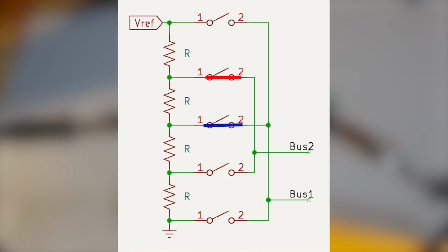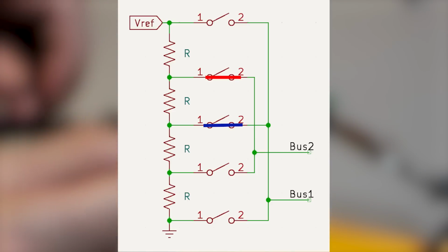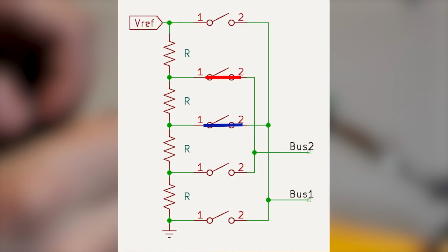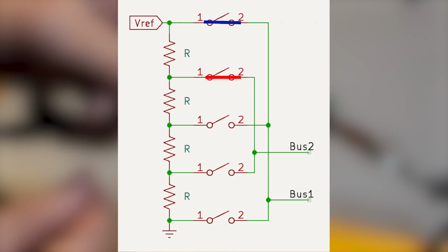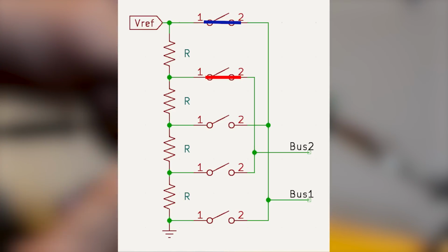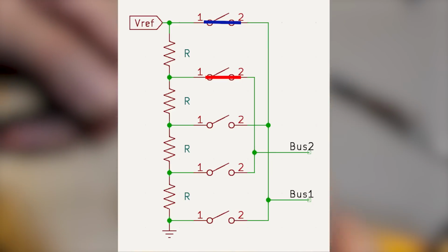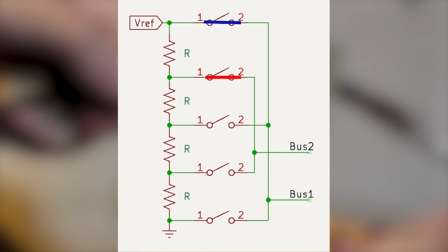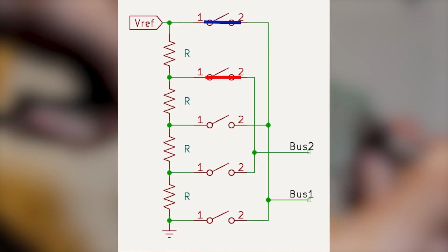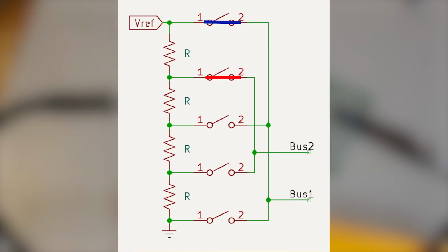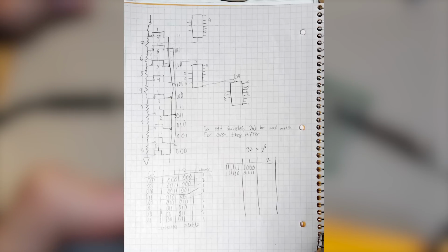In fact, when using this system, each bus will alternate between being V-low and V-high. And increasing the input code will only toggle one switch at a time, which means each bus will take turns incrementing their count. This reduces switching disturbances on the output, and even better, it greatly reduces circuit component count. You will, however, have to spend some time figuring out how exactly you should decode the main input to each of these buses. And after some time brainstorming in my notebook, I found the solution.